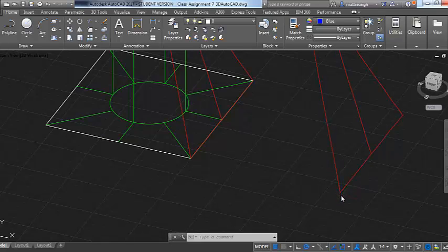When I'm pressing across press brake dies, it's not necessarily going to be on the die until it starts grabbing up in this area. So you'll have this little jog of area that didn't span across the bottom die in a press brake, that'll need to be almost hand hammered over to make this weld seam.